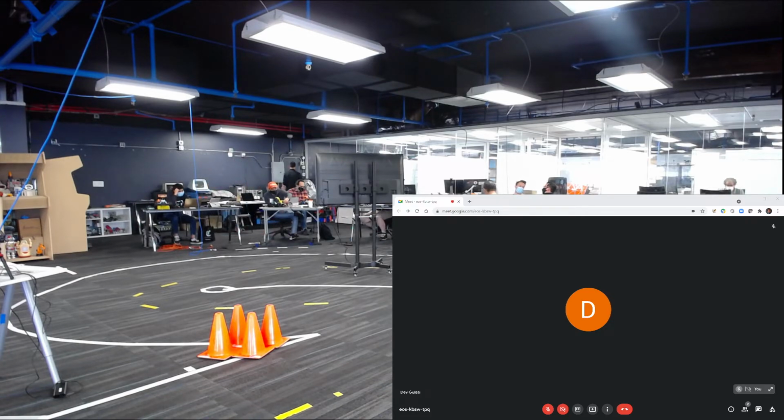It's a little bit different because there's a package that's shared between the VESC driver and a couple of the drivers that are in Autoware.auto, but the version that works with the VESC driver is not the same version that works with the drivers in Autoware.auto, so you have to skip those drivers in Autoware.auto in order for it to build. So this is a colcon build command, just skipping those drivers that don't work with the other version of that common package. This is creating a new document. Yes. Yeah.